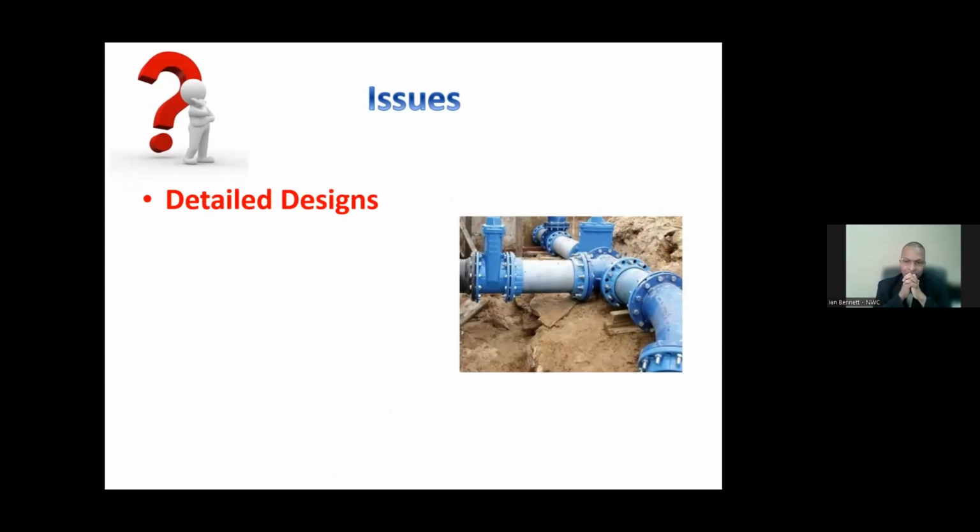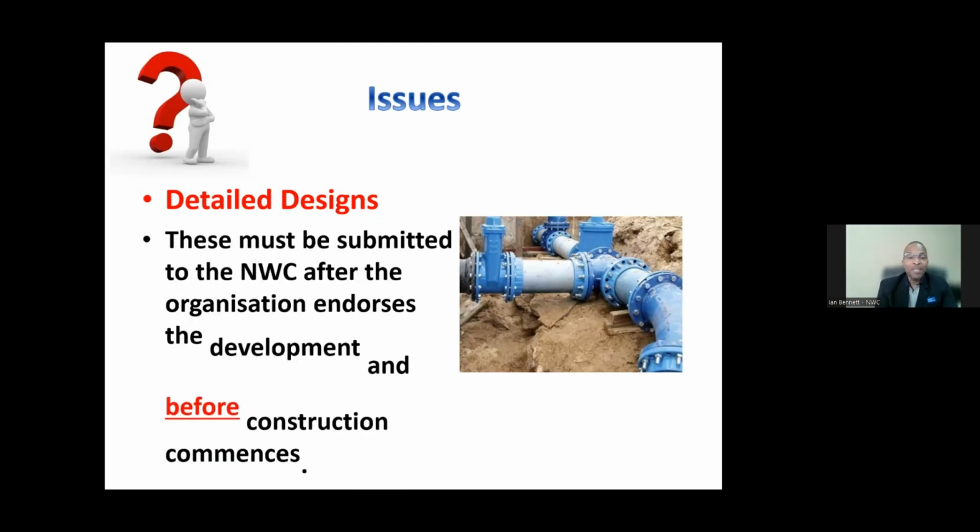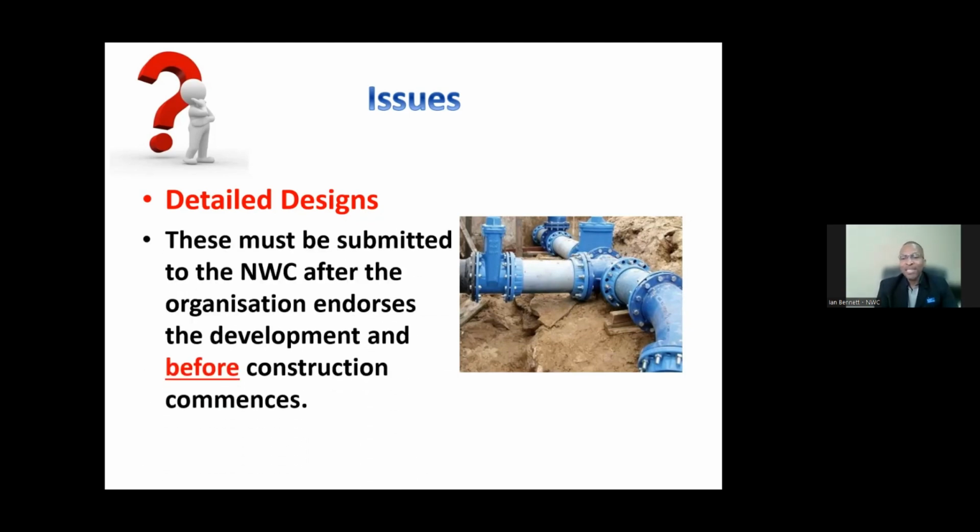Detailed designs. Many persons, when they submit their applications to us, just show the pipes by a line. They give some level of detail, but we do request detailed designs. Are you putting flange fittings? Are you putting socket joints? Are you putting Victaulic couplings? What are you putting in there? What is it that you're doing?